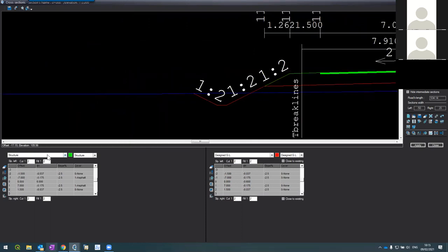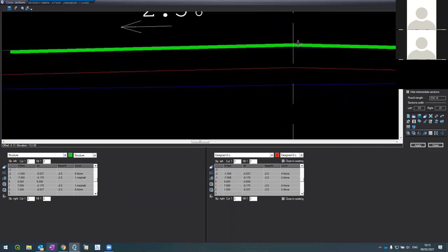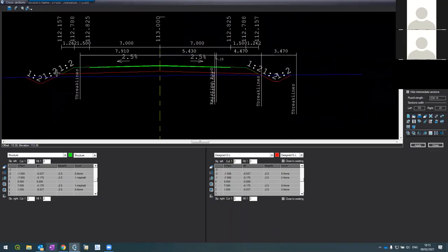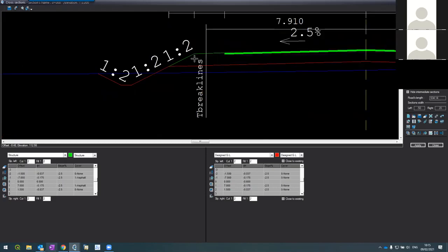And then first of all, we designed the structure total width. How did we do it? We did it by defining the design ground level, the subgrade level. We went from here 60 cm down, so here it is 0 minus 0.6. And from here, we continue until this point, meaning 7 meters and 1.5 meters. From here, the software knew how to complete by itself.